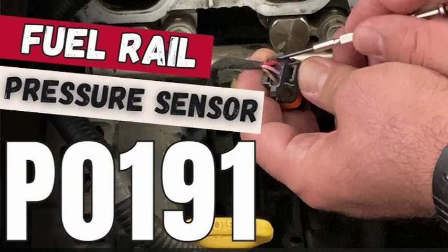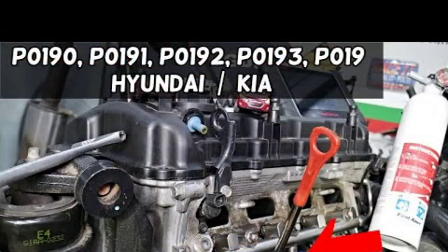Rough idle. The engine may idle rough or stall when the P0191 code is present. This is because the PCM is not able to accurately control the fuel injection pressure. Hesitation or stumbling during acceleration. The engine may hesitate or stumble during acceleration when the P0191 code is present. This is because the PCM is not able to accurately control the fuel injection pressure.